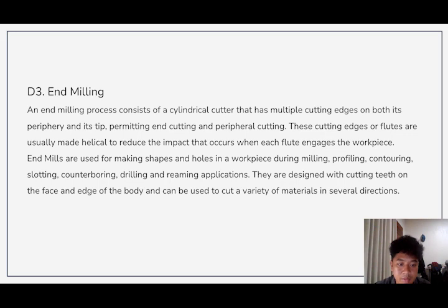End mills are used for making shapes and holes in workpieces during milling, profiling, contouring, slotting, counter boring, drilling, and reaming. They are designed with cutting teeth on the face and the edge of the body and can be used to cut a variety of materials in several directions.